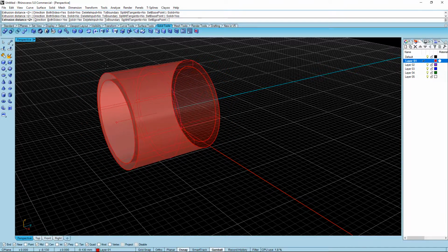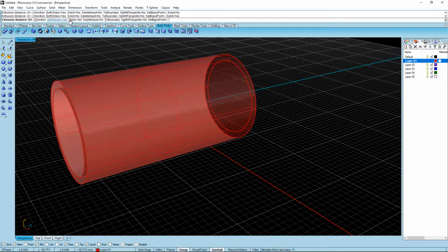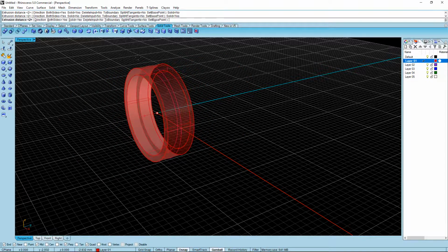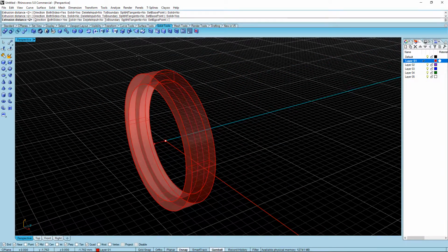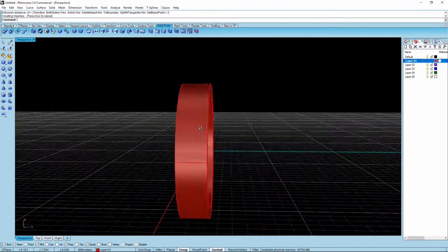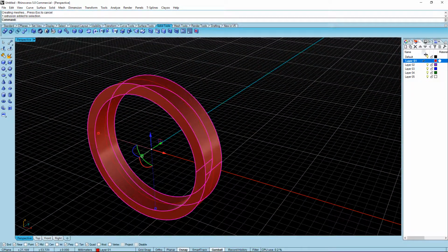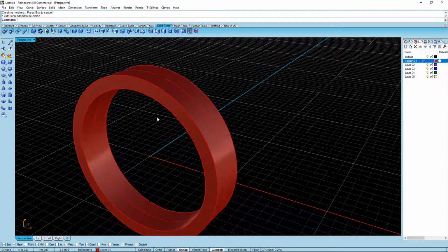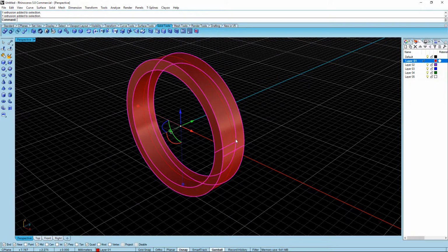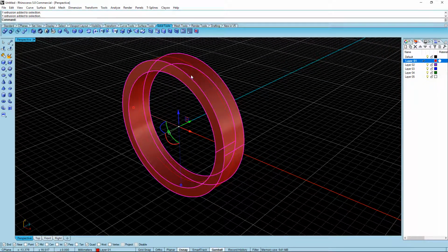Now you should put in a value. When Both Sides is active, if you type 2, the program extrudes the curves 2 mm on each side. So the final object would be 4 mm. Type 2 and press Enter or right-click on the mouse. I want to put the new object into another layer. Select the band. Then from the Layers panel, right-click on one of the layers and choose Change Object Layer.